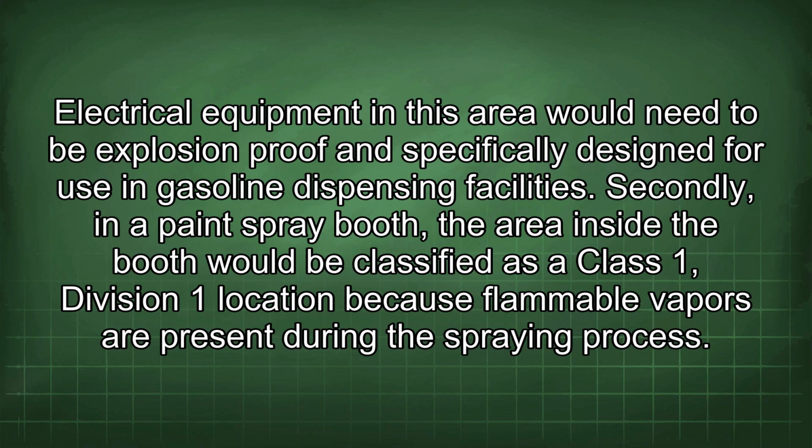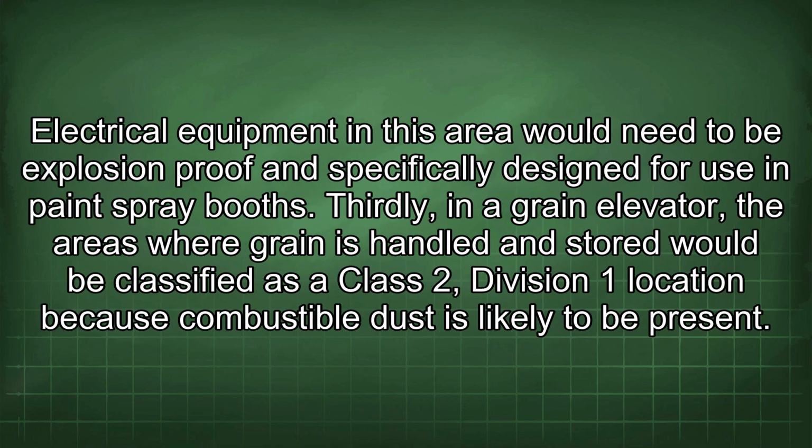Secondly, in a paint spray booth, the area inside the booth would be classified as a Class 1, Division 1 location because flammable vapors are present during the spraying process. Electrical equipment in this area would need to be explosion-proof and specifically designed for use in paint spray booths.